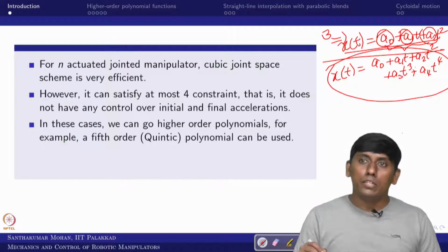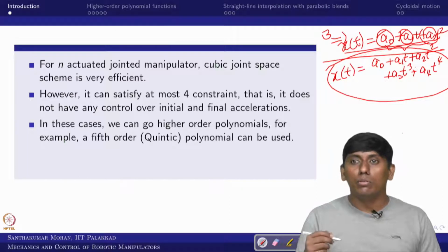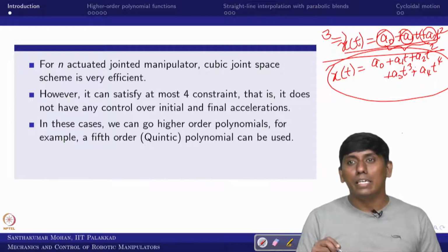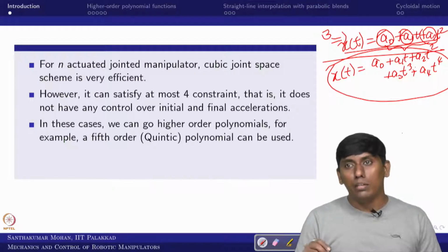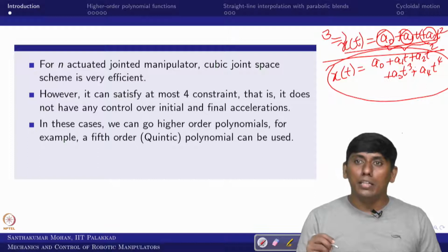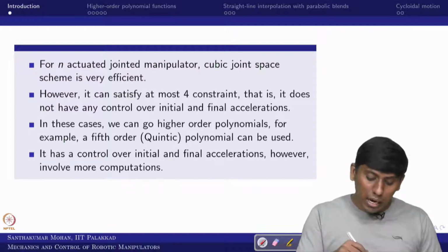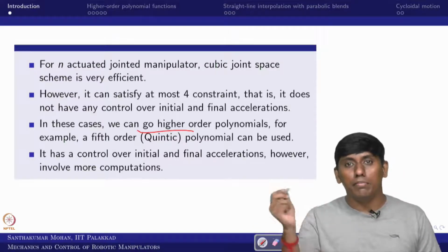Further, the coefficients can be prone to becoming unstable. But if you use an odd order of polynomial, the number of unknowns and the number of equations become equal, both even, and the equations are stable. That is the whole idea. That is why we use higher order polynomials like fifth or seventh: third, 5, 7, like that.